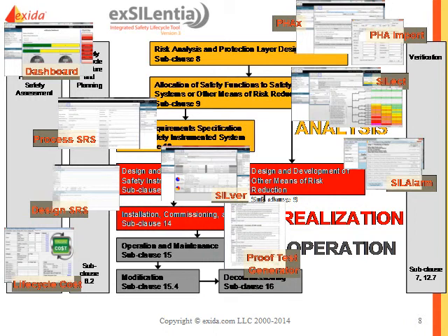One out of one sensor may be less expensive than 2 out of 3 sensor voting, but over the life of the system, there are fewer proof tests. For example, the overall life cycle cost of that 2 out of 3 voting may be cheaper than the 1 out of 1. Of course, it depends on your specific rates, etc., and procurement costs, which are all parameters that you can specify.